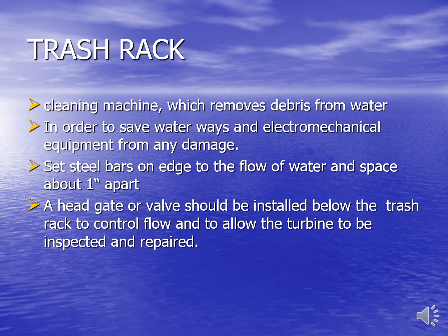A trash rack you have to provide at the water intake, so we can remove the debris from the water, and it is also required for the cleaning of machines. In order to save waterways and electromechanical equipment from any damage, we have to provide the trash rack. Steel bars are set up at the edge, facing the flow of water, spaced about 1 inch apart, right?